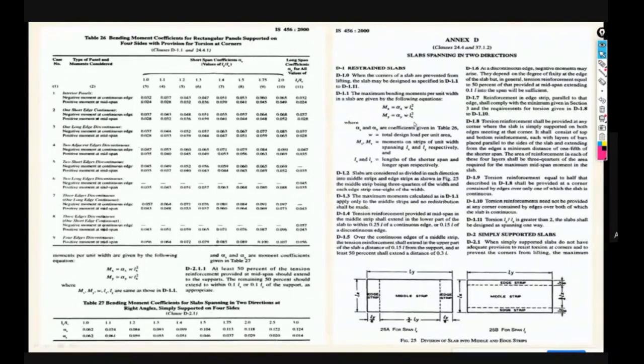Yes, I want to ask one question. Whenever there is a two-way slab, and on that slab there will be a wall for 1 or 2 meters which does not have a beam beneath it, how can we consider the load from that wall? Actually I think I already gave the answer to that question in the first session. Basically, whatever wall we are considering, from the structural engineer's point of view, we have to consider a beam below the wall. Yeah, exactly.